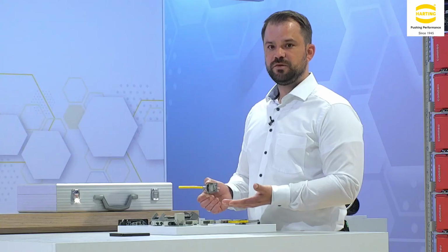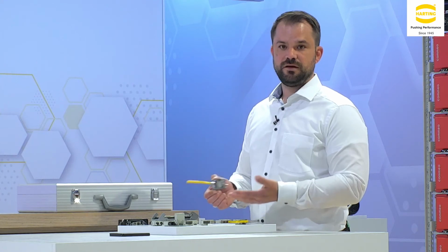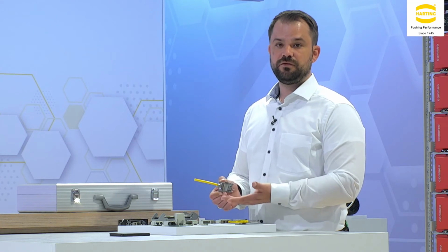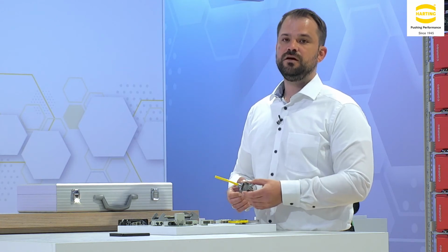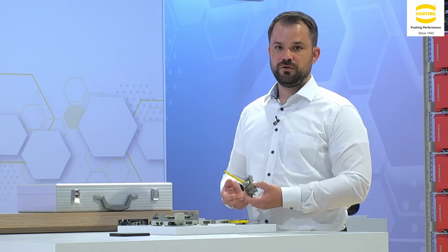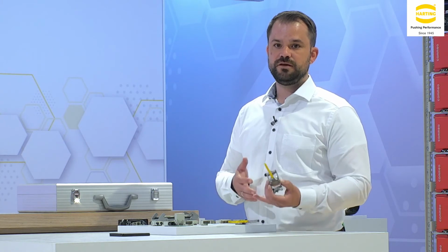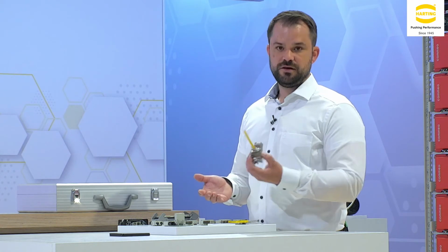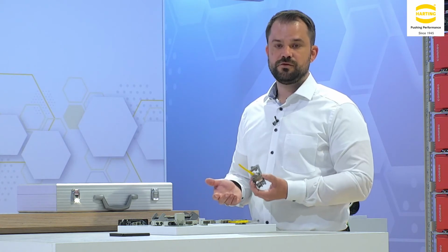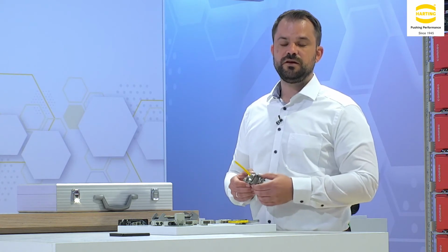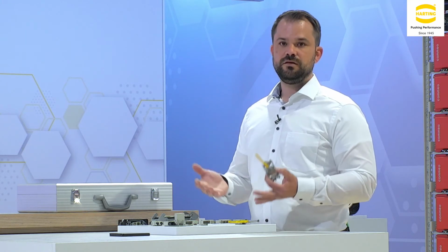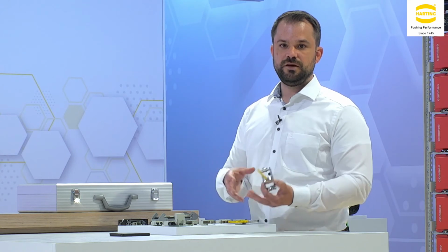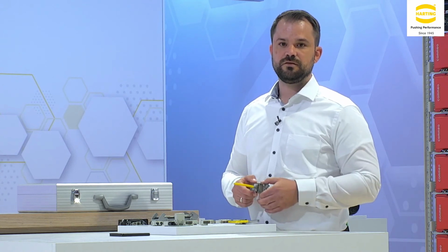The shielding principles are handled differently within our group of customers. So we offer both variants. You can order the module with the shielding spring, bringing your shielding potential to PE, or you can order the gigabit module or megabit module or shielded module without the spring. So you have the shielding taken away from PE or being singularly transmitted within the connector.